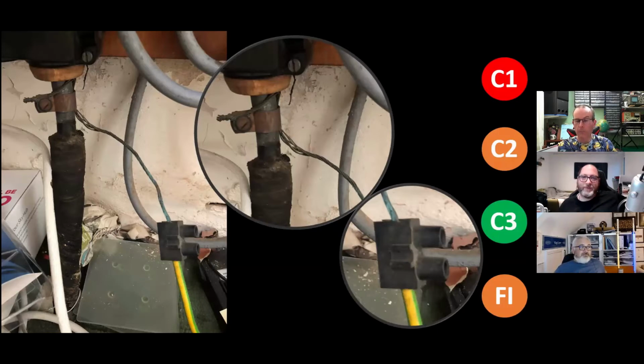This is something, I think what's happened here is there's obviously an old copper clamp there, and what looks like a telecoms earth, and somebody has used that to connect the earthing conductor to via a connector block. So what would you code that as? It's obviously a DNO job, obviously.